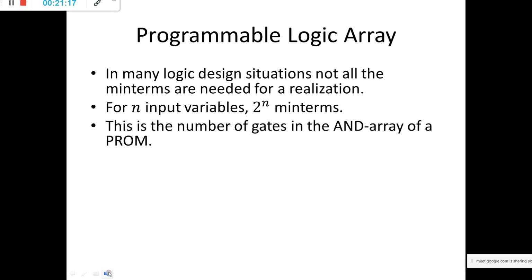This is the number of gates in the AND array of a PROM, isn't it? PROM is characterized by 2 raised to n cross m. PLA is characterized by n cross p cross m. 2 raised to n is the decoder output. M is the output line, right?